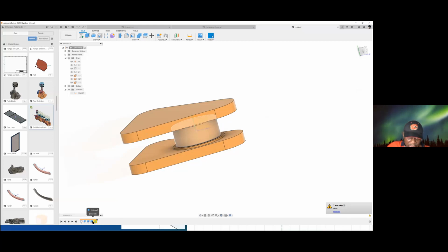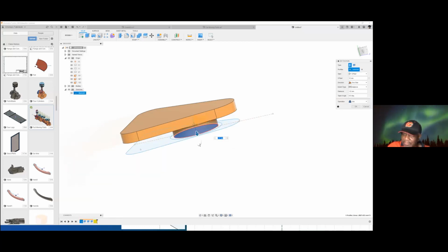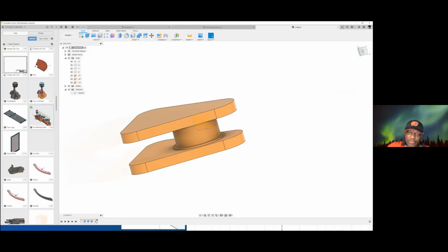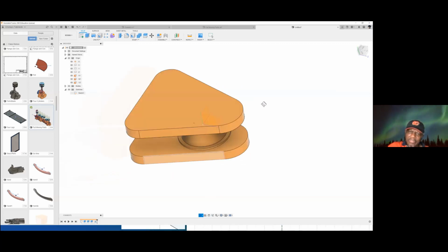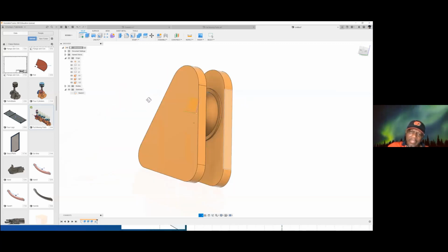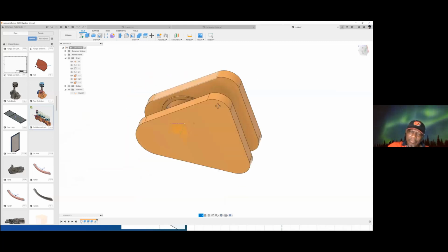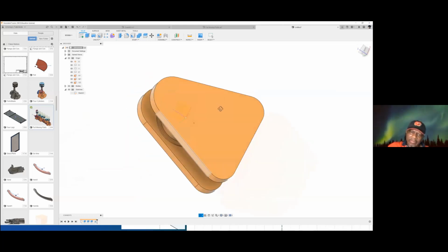The third one is to edit the feature. The offset now is 15, and the distance is minus 15. Minus 15. When we do that, you see again the problem we had before has gone. This may be better than before. So this is the space for our connecting rod now.